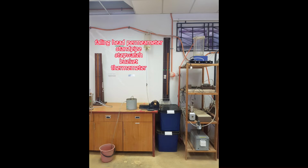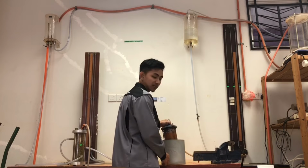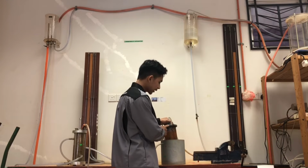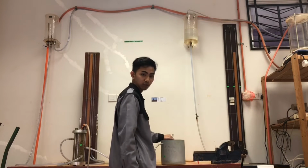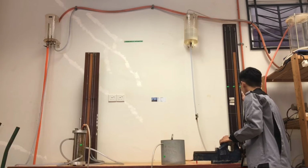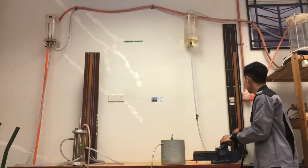Okay, let's go to the last experiment, which is the permeability falling head test. As you can see, this is the apparatus for the experiment, which is a falling head permeameter, standpipe, stopwatch, bucket and thermometer. For the first procedure, place the whole setup in the bucket, partially submerged in water. And then the sample should be tapped to make sure that no air bubbles are trapped inside the sample. And then open the valve and fill the water into the standpipe to a marked initial height of the standpipe.